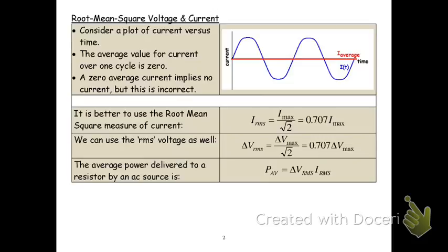If I touch something that's high voltage and it's potentially high current and it goes through, it's going to go down one side. It might give me a heck of a shock, but that will take it right across my heart. And that's when I die. So they've been trained, you know, they put their hand in their pocket, so they're much less likely to grab two things.